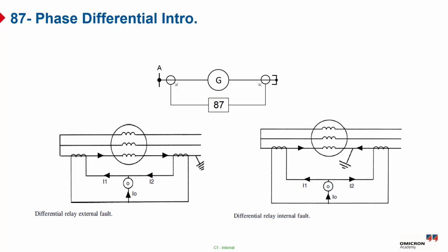Normally for a generator more than 5 megavolt-ampere, if the fault occurs inside the protected area, the differential current Idiff is calculated unequal to 0. So Idiff will equal I fault. But if a load current flows through the protected area, or under external fault conditions, the differential current Idiff is calculated to be 0. So the calculated value of Idiff is sufficient to distinguish between a short circuit current inside or outside the protected area, or a flowing through load current.